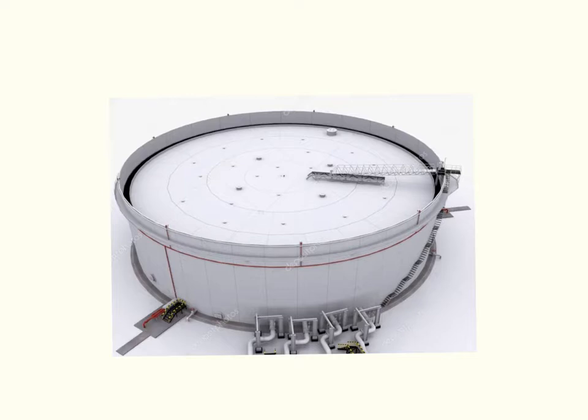Anything directly above the tank roof is a Zone 1 location. This area extends from the top of the roof to the top of the shell, which is what we're showing in here, and essentially it's this part in here.